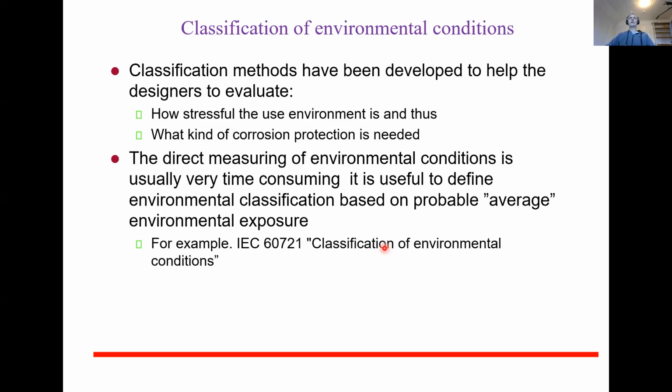On the other hand, if the conditions are extremely severe, you may need to use really hermetic sealing, meaning that you need to push the moisture diffusion down to extremely small values. And that could be very costly. You need to use ceramic packages, which can be 10 or even 100 times more costly than organic packaging, and so on.